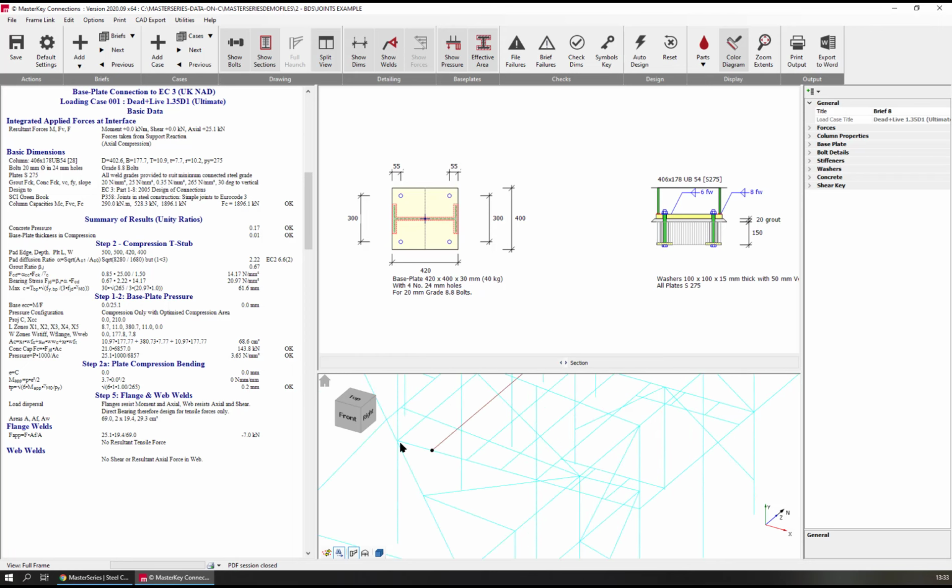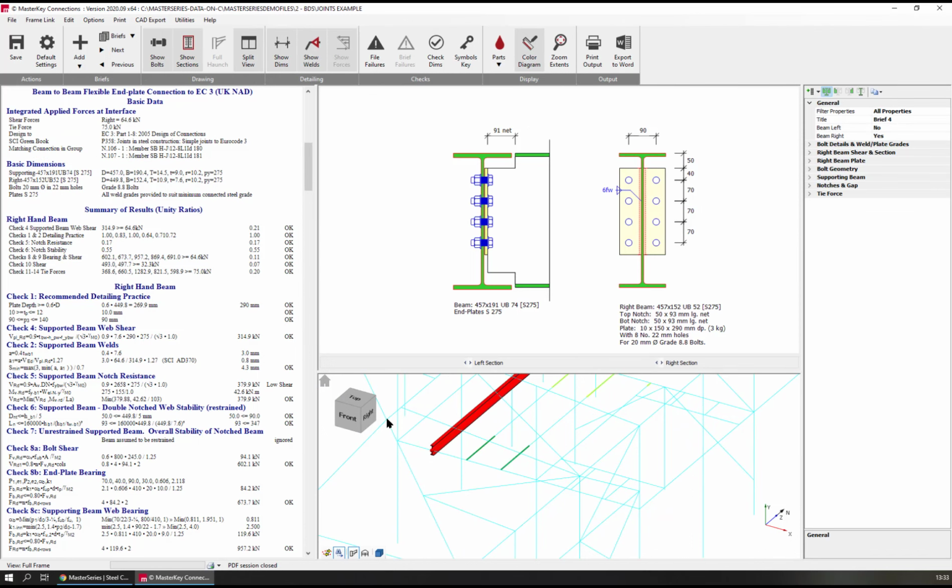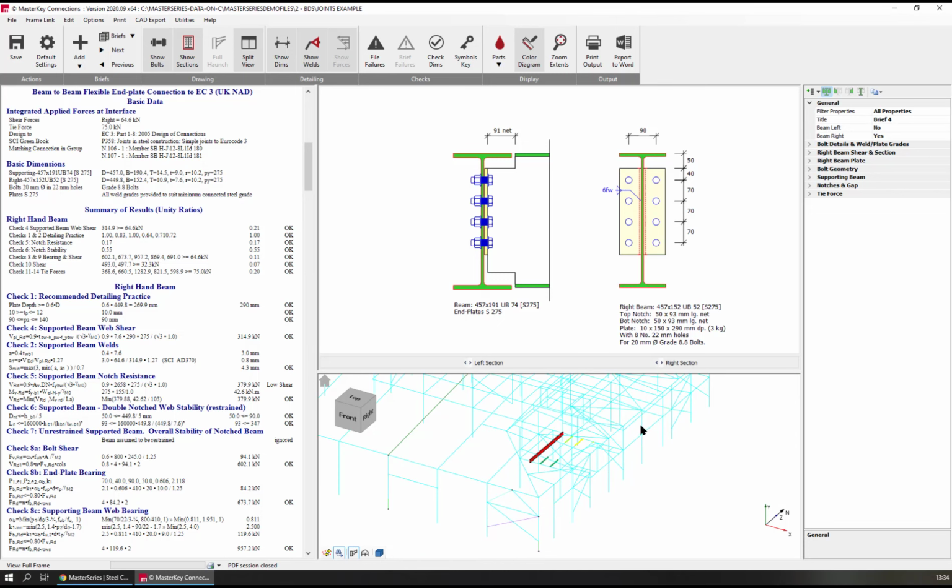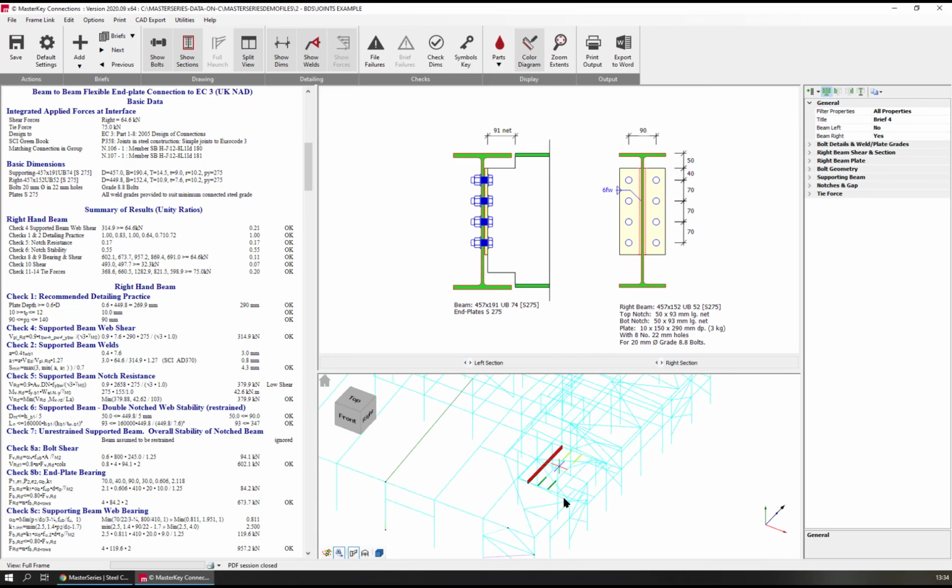If we want to then look at this one, we'll see all of those were all designed the same, all these three different designs. And not only does it design them, it always tells you which ones have also been designed. So it's at node 106 and 107, but more accurately on H to J, and it's giving you the ID. So because we haven't got grid lines everywhere, it's giving us subgrid lines. Again, very, very useful and flexible on the software design. So it is such a simple, beautiful program.